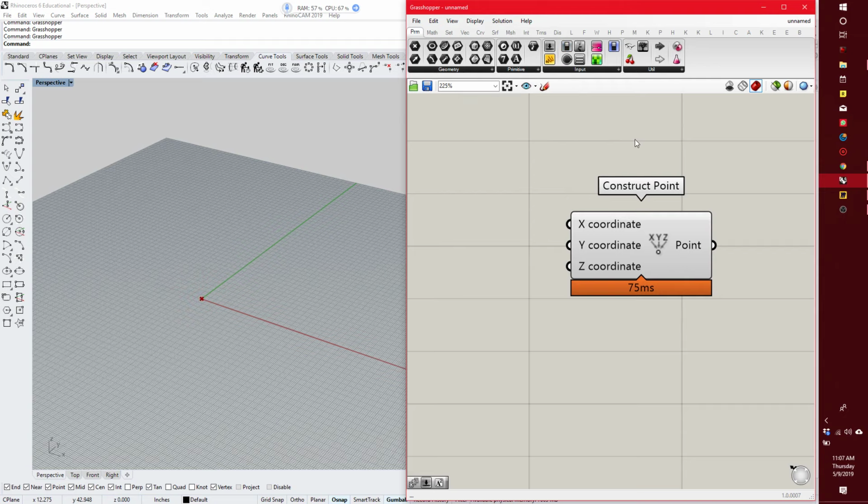Sometimes you might see a mesh or a polysurface that has a boundary, and the surface seems like it doesn't quite meet the corner, almost like the surface is offset or missing from that corner. That might just mean that you have it on low quality or custom quality. If you put high quality, you'll see that start to fill in. You'll see the most accurate version of the geometry that you're working with.